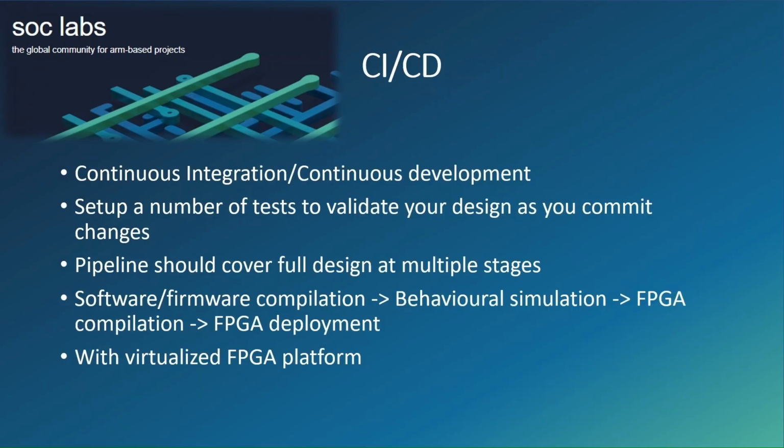What we've done with these FPGA boards as well is made them into a virtual environment. So what that allows us to do then is continuous integration and continuous deployment, so that we can validate our design as we go, as we commit new changes to the Git. We've tried to make this cover the full design as much as we can, and it goes through all of the stages. So the software compilation, behavioral simulation, FPGA builds, and deployment onto the virtualized FPGA platform.